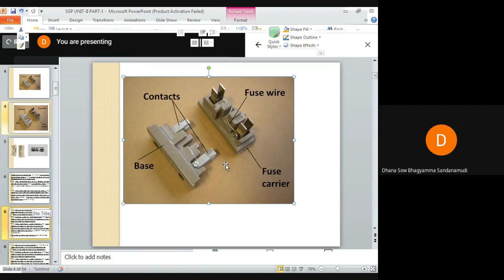Tinning means providing a varnish-like coating above the copper, which is malleable and ductile. Malleable means it can be hammered, and ductile means it can be made into a very thin cross section. The main purpose of tinning the copper is that a bluish white coating is provided above the copper conductor so that it can be protected from oxidation, in simple words.